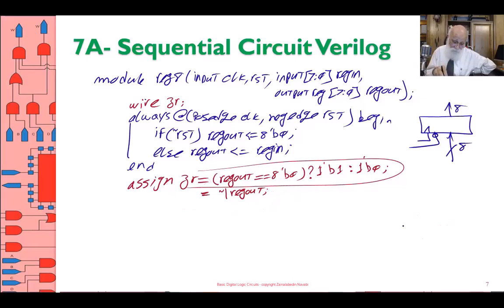The key thing is here that if you have something like this, here, let me show you here. This is the NOR reduction. This is 0. Okay. The key thing is, if you have a situation like this, never ever put the 0 inside the always statement. Anytime you put something inside the always statement, automatically that becomes a register.